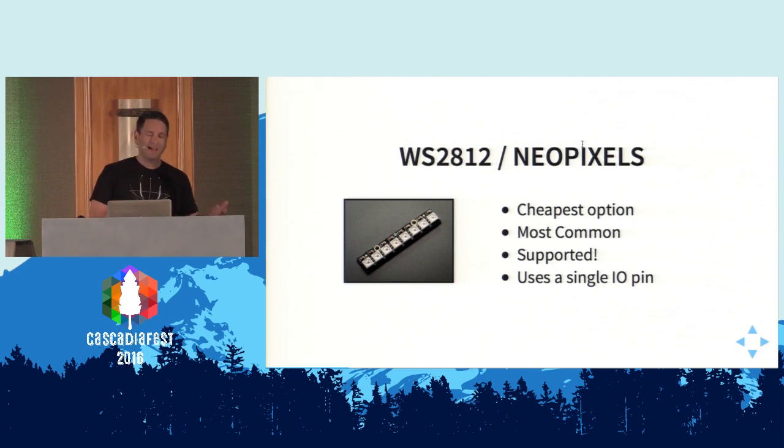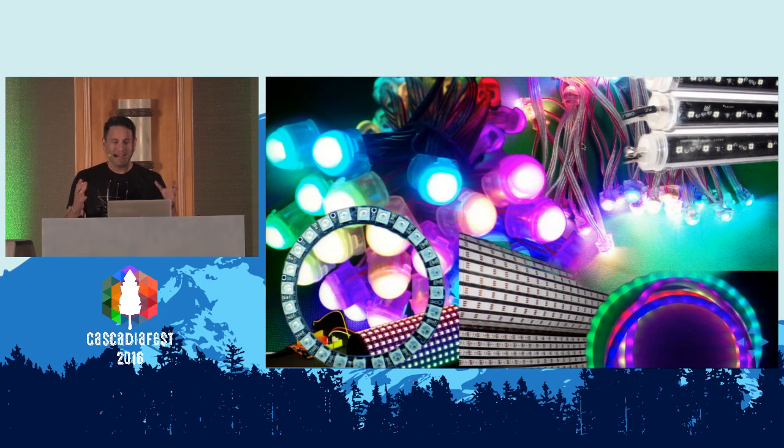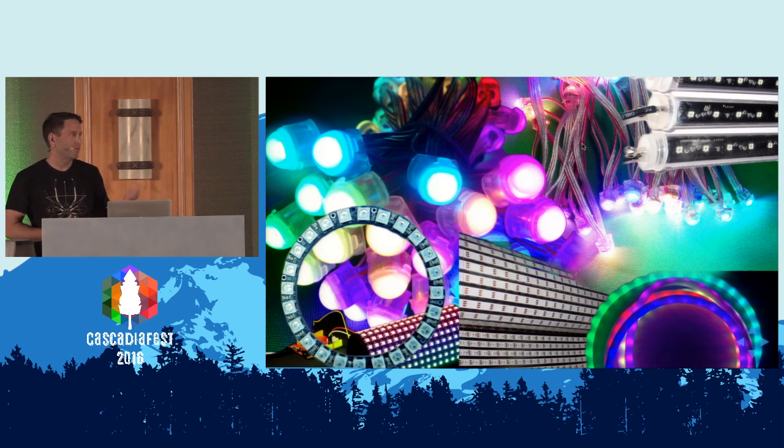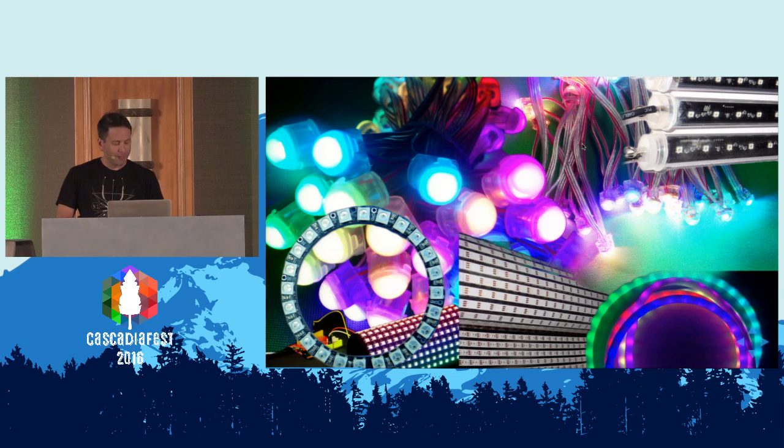If you see tutorials about how to work with individually addressable RGB LEDs, chances are they're going to be the NeoPixels. They're supported by a whole bunch of different libraries and different languages. And the nice thing about them is they actually only use a single I/O pin. So if you're working with really small microcontrollers and you only have like 3 pins, it's great because you can control 128 LEDs with a single pin. The other thing that's great about them is that they have all kinds of different form factors that you can get. Christmas lights, meteor lights, grids, rope light, rings. Pretty much if you can think about something that you want for NeoPixels, chances are they probably have them.